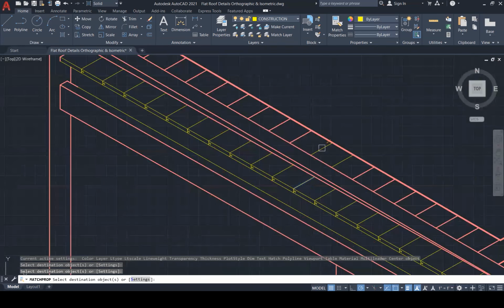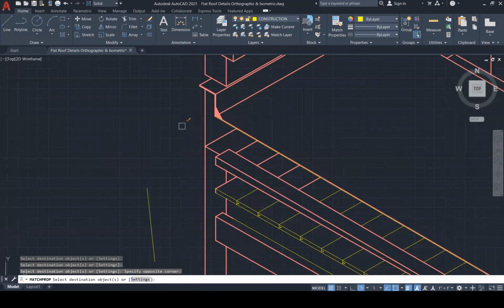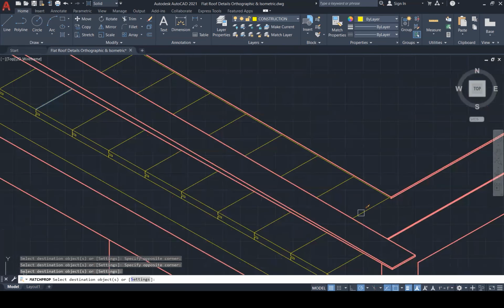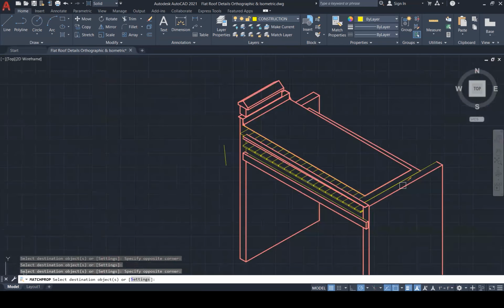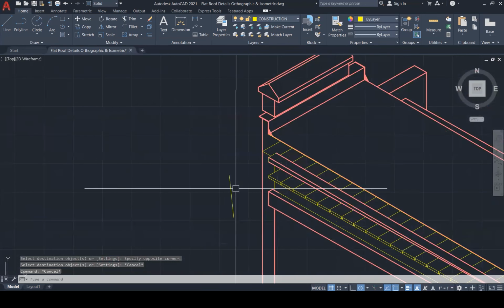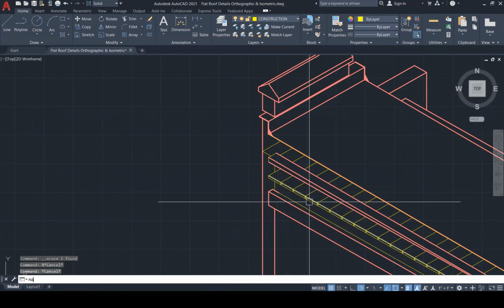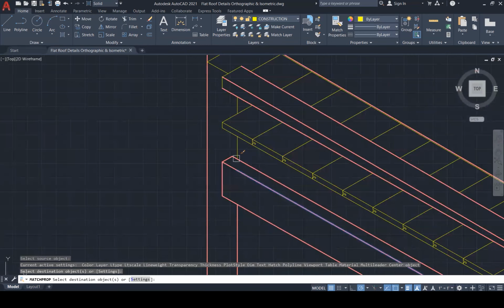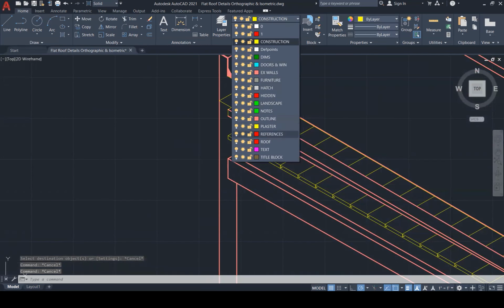I've got to put these ones back here. Having knowledge of how to green and blue grab is very important, and it comes in handy, especially when you're doing these drawings. So you can grab multiple items at one time. So I'm going to put this in as reference.